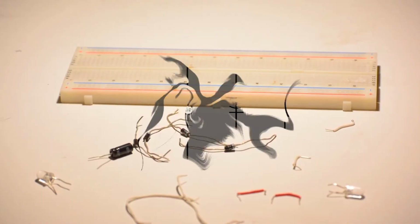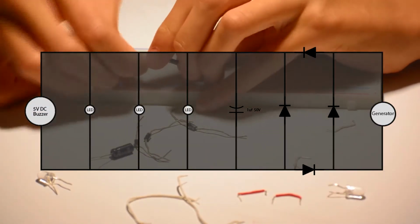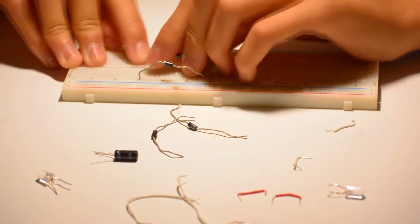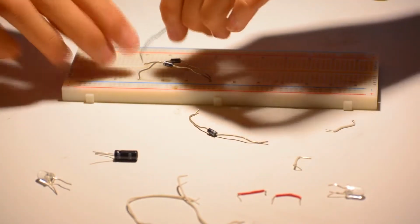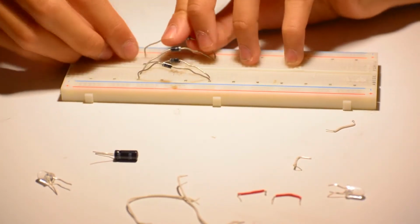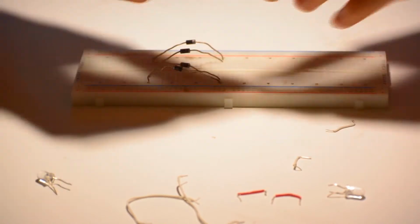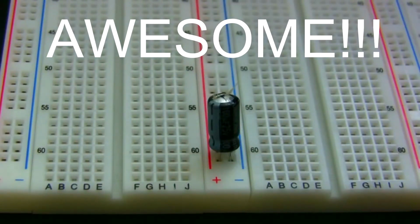Now it's time to construct my circuit. Here's the schematic diagram that I will be constructing on my breadboard. I'm going to start by building my diode circuit. By arranging 4 diodes in a unique way, I can make it so that when the generator is generating reverse polarities, the LEDs will still light up. This could occur when the generator is spinning in opposite directions. The circuit is very important because it can prevent the capacitor from exploding due to reverse polarities.